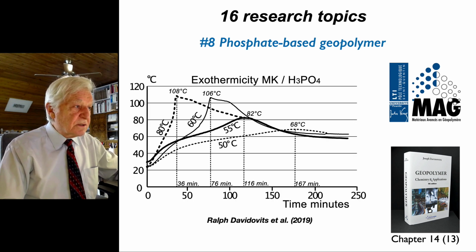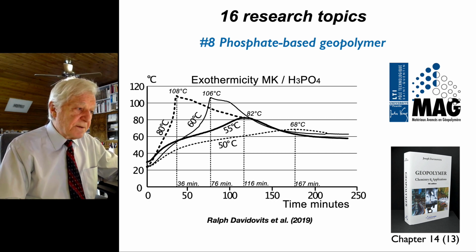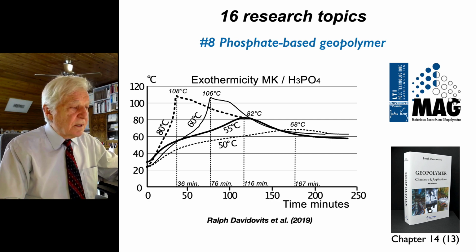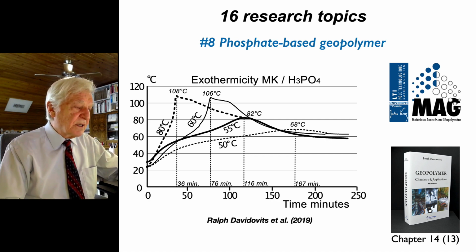The first is the exothermicity. The phosphate-based geopolymer is carried out with the reaction of Metakaolin and phosphoric acid. And we performed the same testing as we had just shown for the alkaline medium reaction with Metakaolin and potassium silicate or sodium silicate.